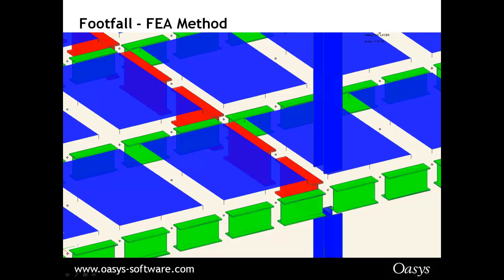Conversely, you can also take a different stiffness value for the concrete. Concrete stiffness is very time dependent, and you're all familiar with short-term and long-term E values or Young's modulus values. For a dynamic case, the E that you can take is even greater than the short-term value. The SCI and the Concrete Centre guides recommend 38,000 newtons per millimetre squared for the Young's modulus. The Euro guides coming out recommend a 10% increase on the actual short-term stiffness, as the drafts do at the moment.